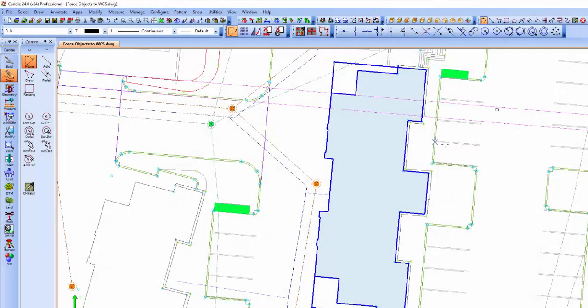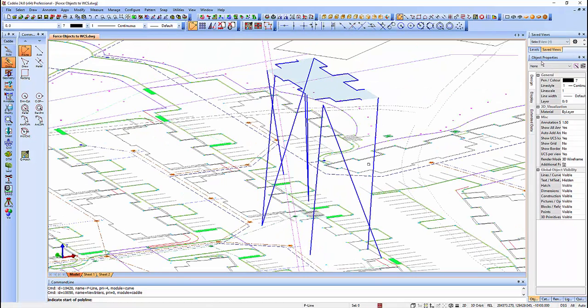So what's going on here? Well, let's have a look at our drawing in a rotated view. And here this tells a much truer picture of what we have. So some of the objects have varying Z values, which means that when we look in plan everything looks fine, but when we look in the rotated view we can see that objects are very much not flat on our UCS, which is actually the WCS here.